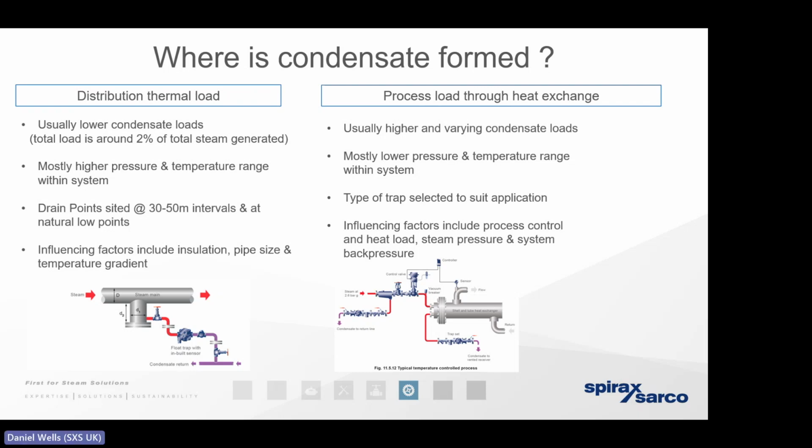The thing to bear in mind is, if we haven't sized the steam trap capacity, allowing for that increased warming up load, those steam traps are now going to be undersized. The condensate cannot pass, and the condensate is going to back up and slowly start to flood the infrastructure. And that's when we find those issues with erosion, corrosion, water hammer, a high heat loss due to wet steam, and a low energy content of the steam slowly creeping up on us over time.